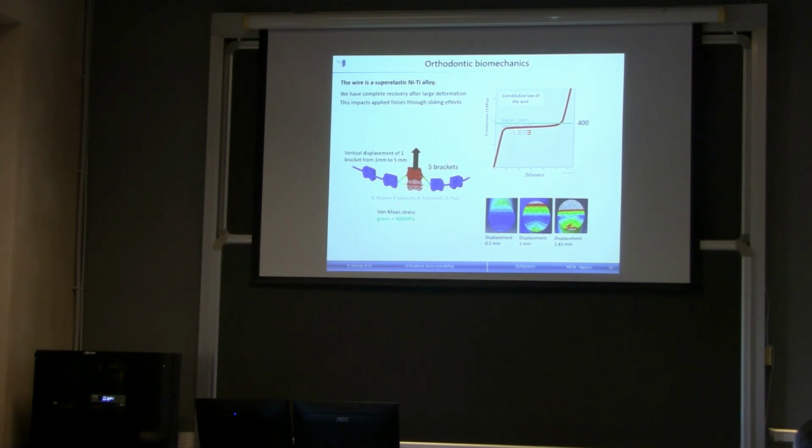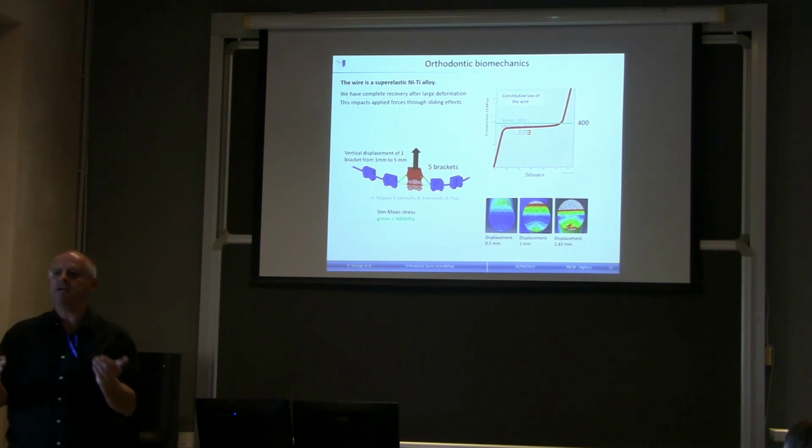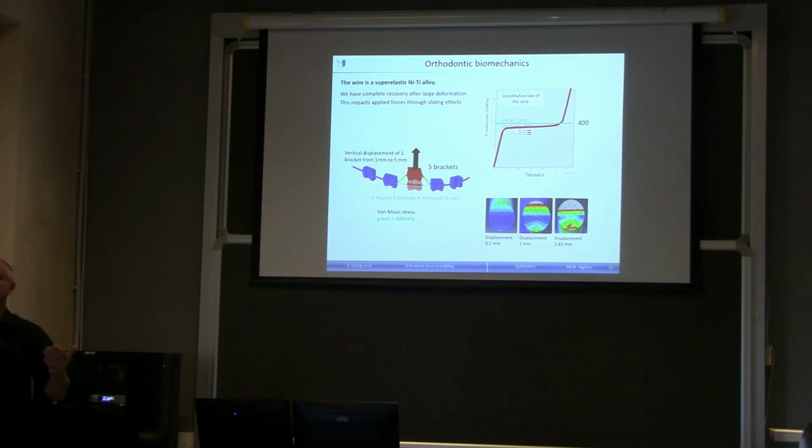When we did a finite element model of the problem we have to deal with, we put the wire inside the bracket, and then we apply displacement in a central bracket, and then we look at the stress distribution inside the wire. What we see is that for small displacement, 0.5 and 1 millimeter, the stress distribution inside the wire remains under the yield stress. Therefore, we have a complete elastic recovery that drives the tooth displacement during the treatment.